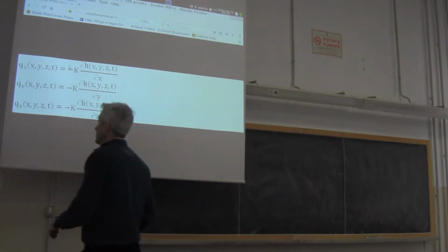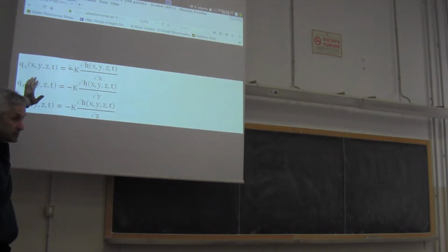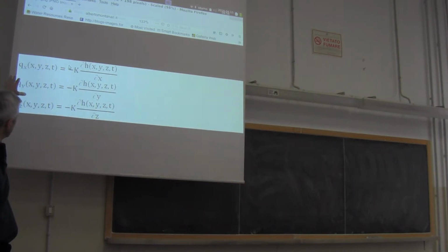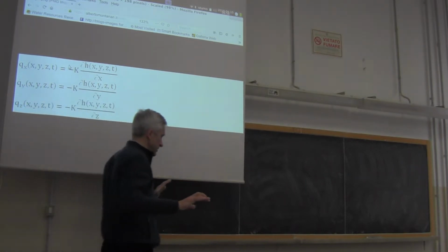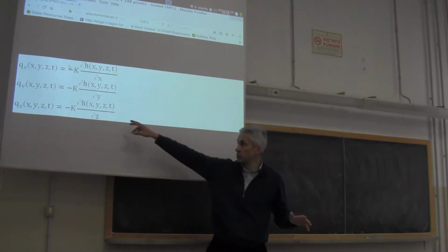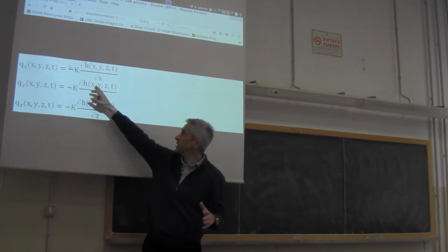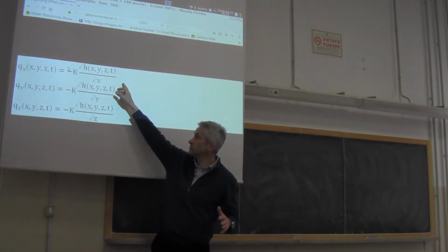So Darcy made, just by lab experiments, he started with a lab experiment in 1D, and then he proved that, of course, the equation could be extended to the 3D domain. What he did was just simply through a pipe, and I will show you a sketch, he measured the relationship between the flow in one direction and the change in head.